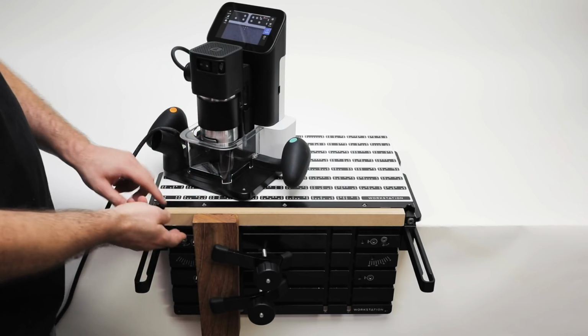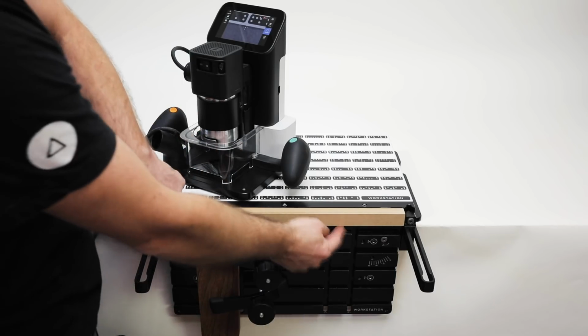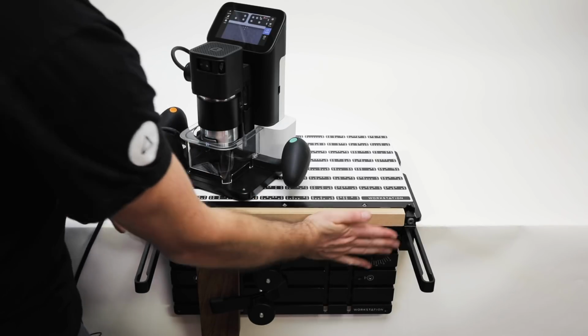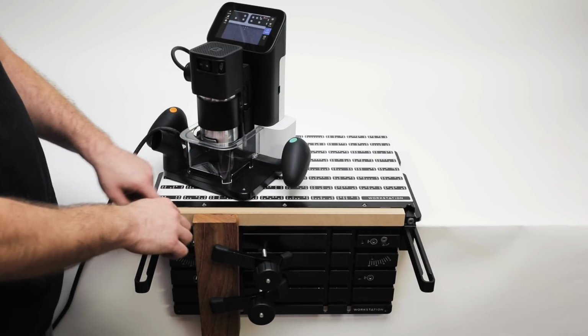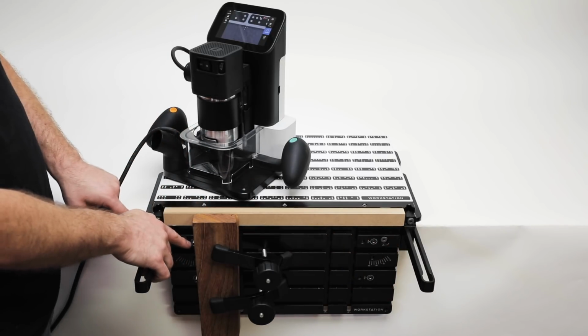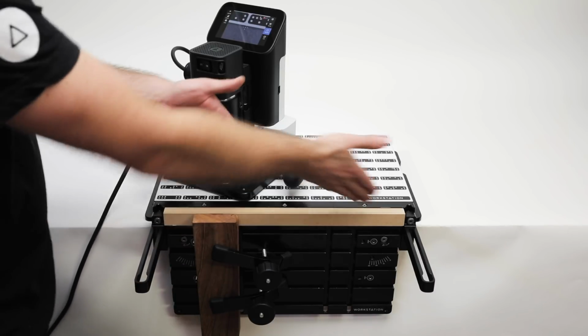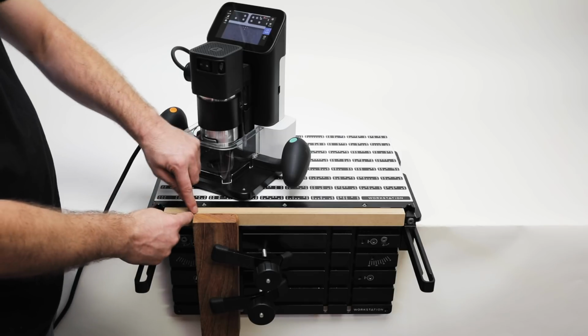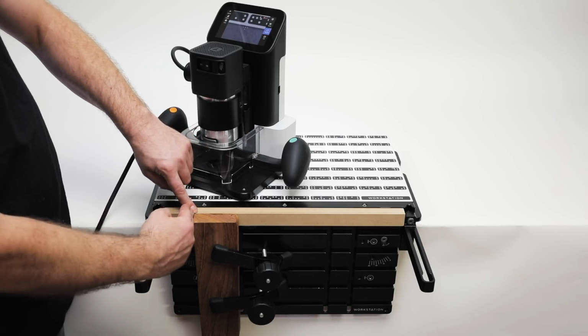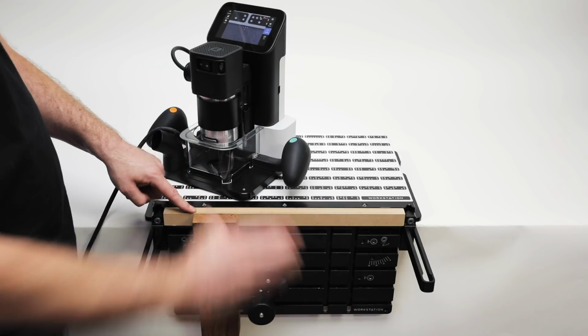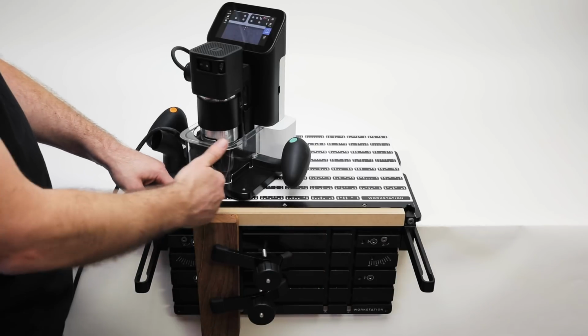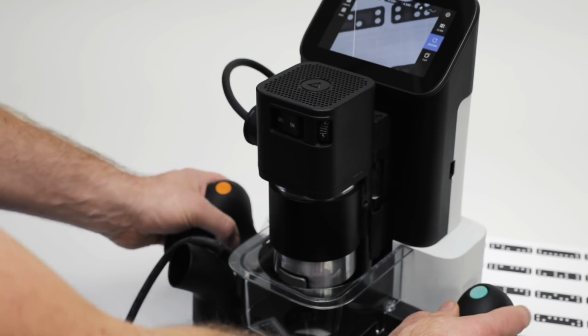Another big performance boost that you get with the workstation is built into the fact that we always index into these same locations with the vertical alignment pins and machined front face of the workstation itself. So you can raise it up and actually grid against the workstation itself, and you can do that once. Then you don't need to rescan when you add stock that indexes against that face and the pins.